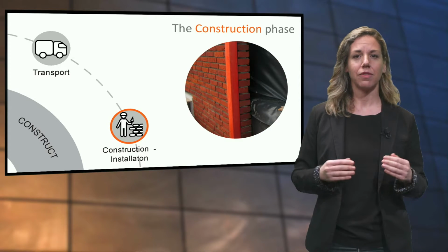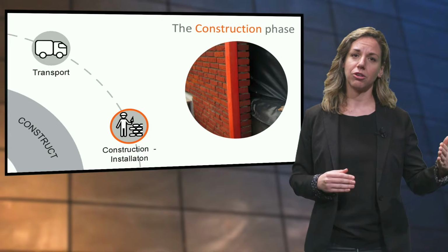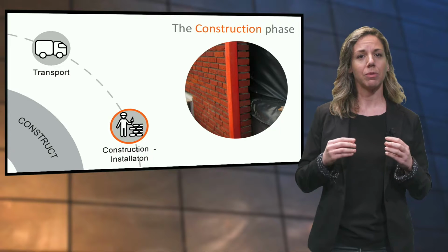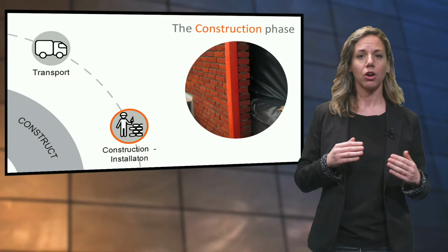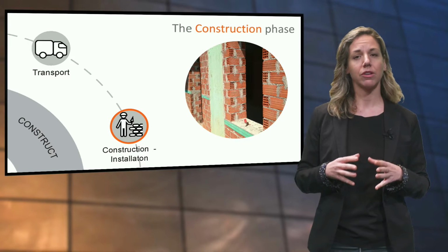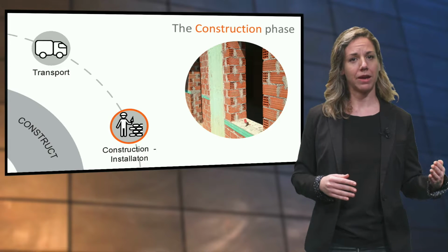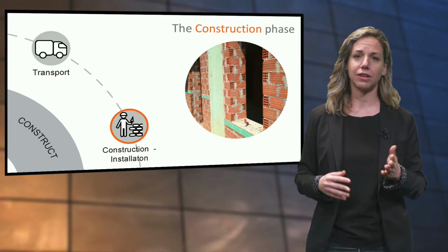For example, facing bricks that are placed as an exterior layer have been manufactured to tolerate water. They are denser and have been fired in higher temperature. Hollow bricks, on the other hand, have better insulating properties, but they are not used as the final surface. They are often plastered or being used at the inside layer of the facing bricks.